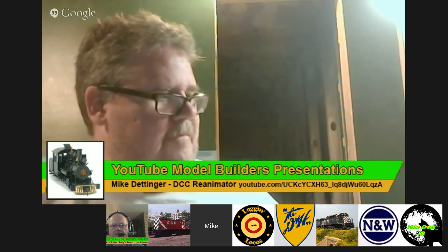We've covered a good bunch of information concerning the DC side of things, and there's not as much to cover on the DC side. You do these to this level, you're talking wiring complexity, but there's nothing different about the throttles. You get really complex with DCC, then you get into signaling and power management, which we didn't talk about yet. If you have a large DCC layout, just like with DC, you have to break it into blocks, but not for control methods, but for power management.